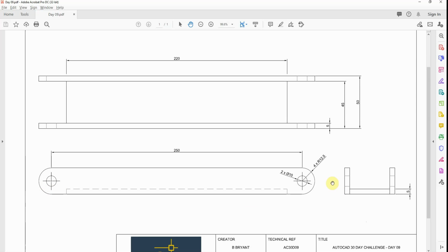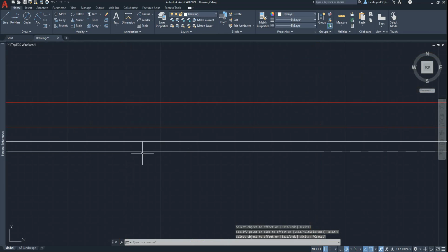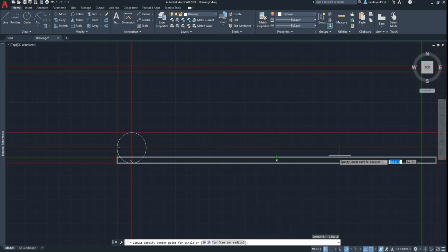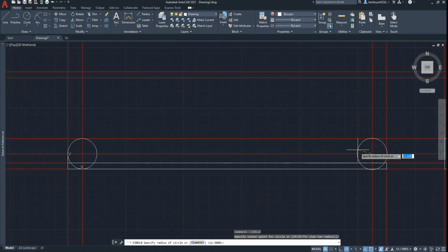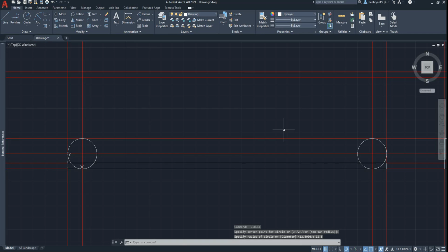Okay, centre line in to put the circles and the radiuses. We know that's halfway through 25, so it's going to be 12.5. Like so. So all we're going to do is then put radius in 12.5, second radius in here 12.5, and then I've got 2 10s, so 5 apiece.